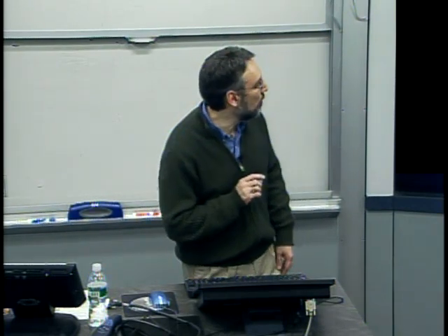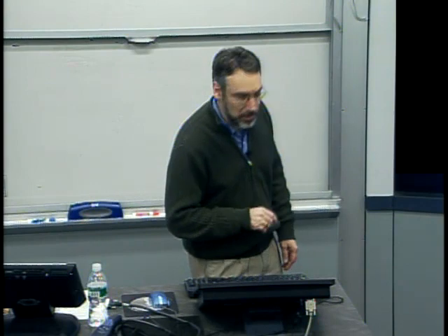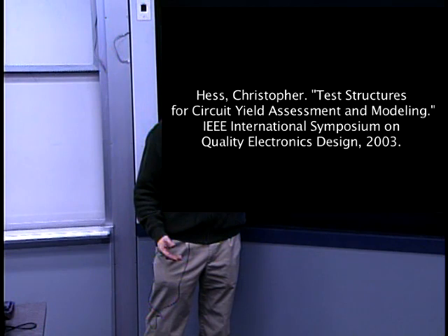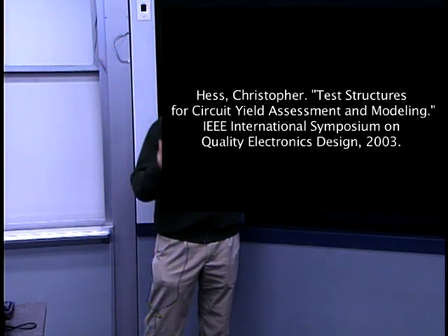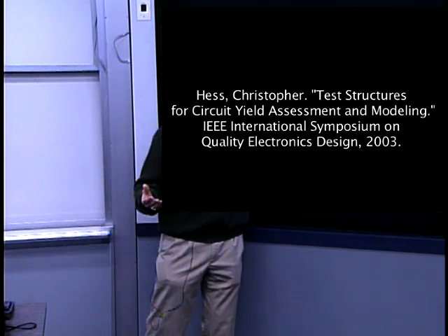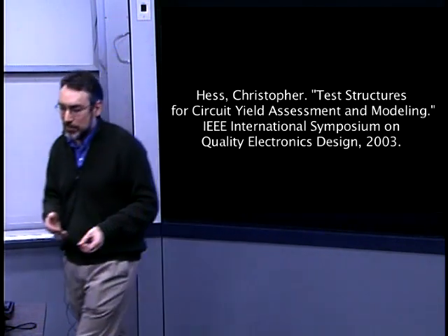But what is becoming much more important, and we mentioned this on Tuesday as well, is parametric control. And in some cases, even these defect controls turn into parametric control problems if what I'm worried about is not so much yes-no functionality, but changes in the resistance of lines because of the presence of defects.